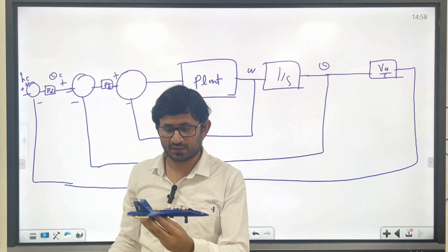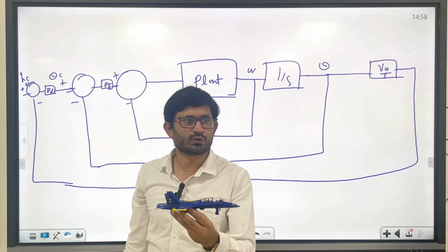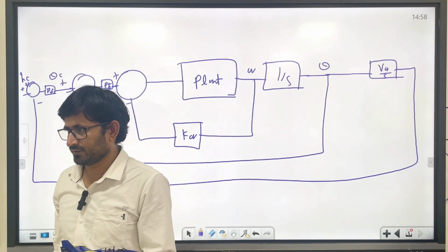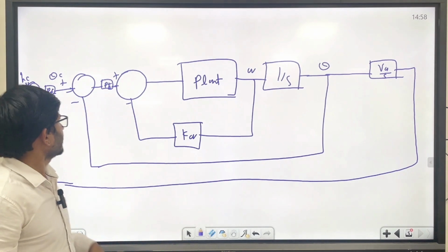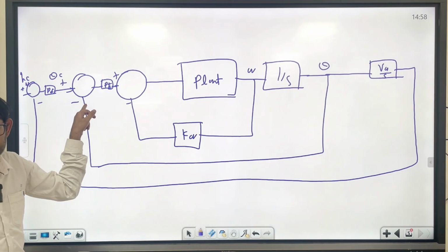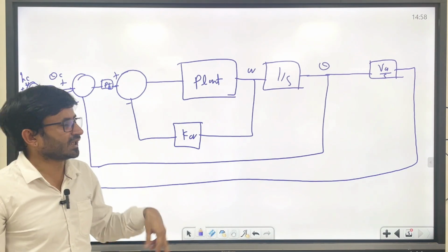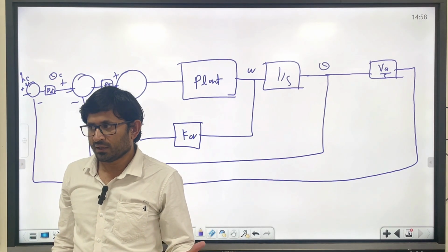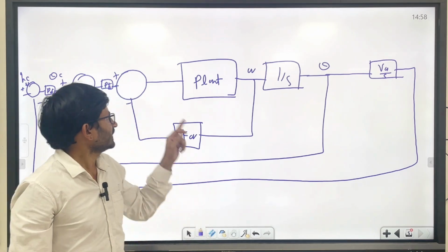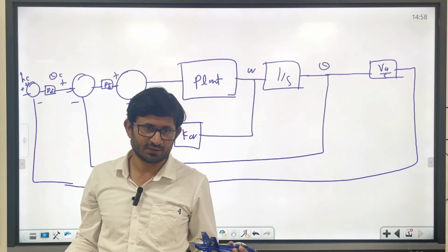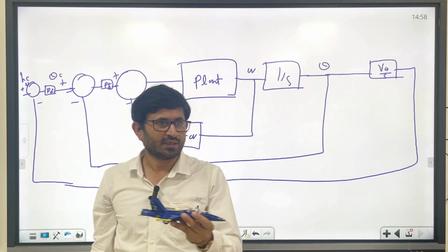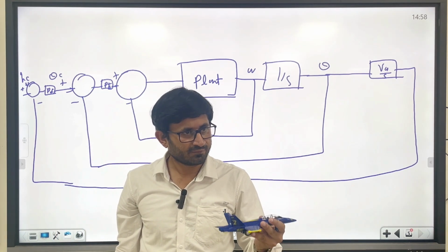Let's say the aircraft is flying and the pilot has commanded an altitude of, let's say, 1000 feet. Accordingly, theta will be generated. In order to attain theta, a Q command will be generated, and to attain that Q command, the elevator will be deflected. That is how it happens here, and that is how you attain steady state level flight.